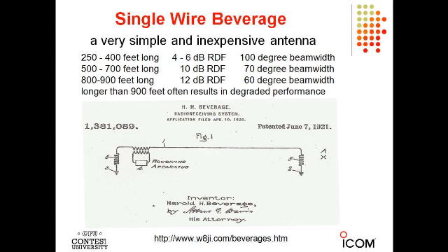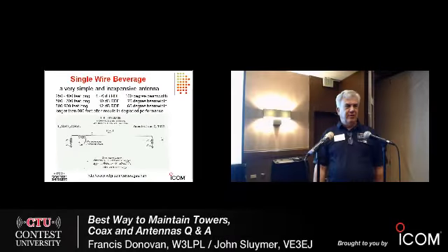Well, how did he do that? Nobody had discovered HF radio yet. The only way they knew how to communicate across the oceans, just prior to and during World War I, was with massive transmitters, hundreds of kilowatts. The transmitters in use at the time were Spark or Arc, which is a little bit different, or during World War I, 300 kilowatt motor generators operating at 24 kilohertz, feeding antennas that were 500 feet high, 300 feet wide, and almost a mile long.